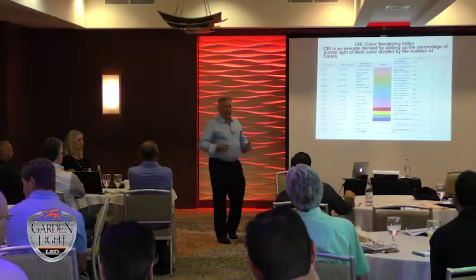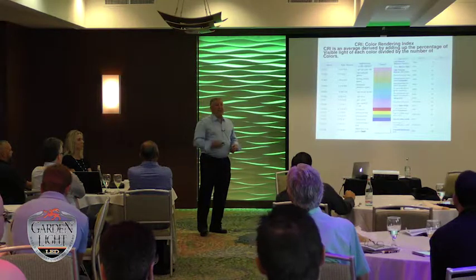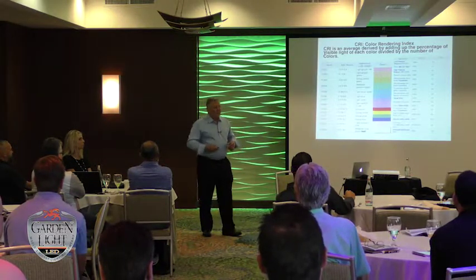The absence of red removes the reflected red coming off of the device or the object that you're lighting, and you get blue. So what does that mean? Well, LED fixtures that are 70 CRI still have enough red to make that look purple under the lowest CRI of LED. So whenever anybody says you got to have a positive R9 value, it's always a matter of what is it you really want to see, because a positive R9 value does not necessarily mean you're just going to get more red. You get enough red out of a 70, but you're going to pay a lot more for it. Now, I like to talk to lighting designers and keep them right around 80 to 85 CRI. 95 is expensive, you lose a lot of life out of it, but there's going to be people that are going to ask for that.